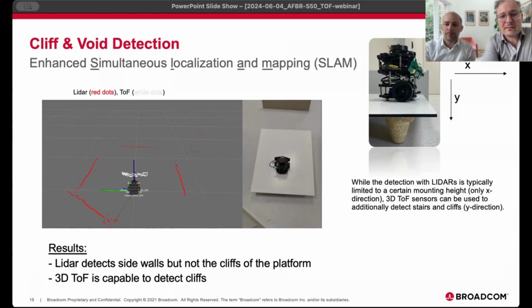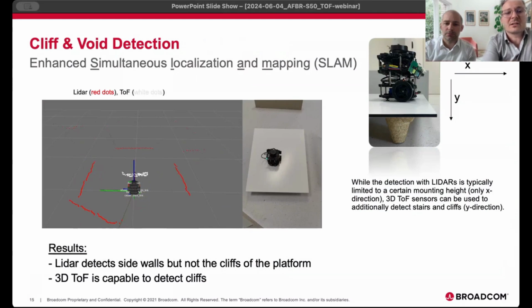If you look at the video again, this is a ROS implementation, for Robot Operating System, which shows the live sensor data of the TOF devices looking downwards to detect the cliff. You can see here that whenever the cliff is detected, one of the sensors shows a moving structure of white dots, which gives you the indication that the cliff is detected properly. And this form of sensor fusion can be quite beneficial to AMR manufacturers or even AMR users.